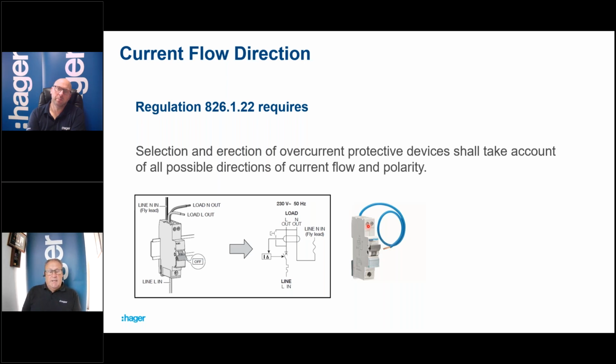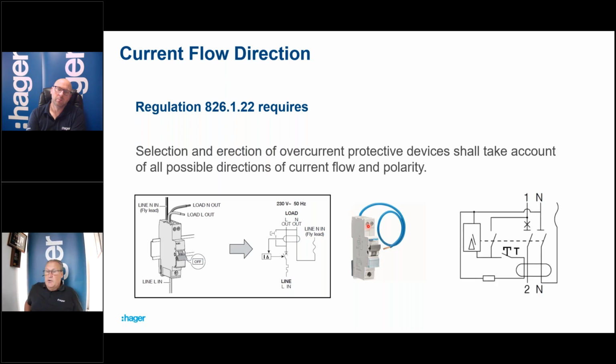Now, that has come to mind recently, but the other thing that's come to mind recently, hasn't it, Paul, is about the neutral switching. Again, is there a small joint on the product that identifies that? Yeah, most RCBOs don't switch the neutral. That's not really a new requirement.